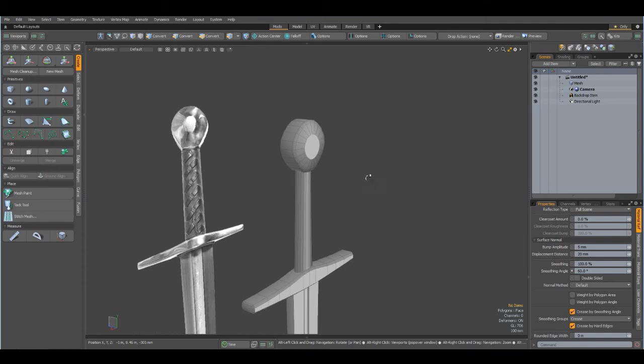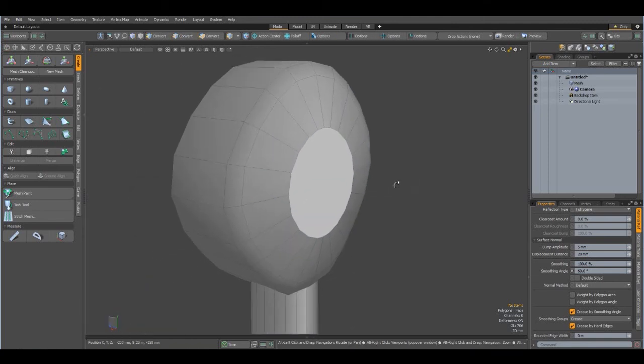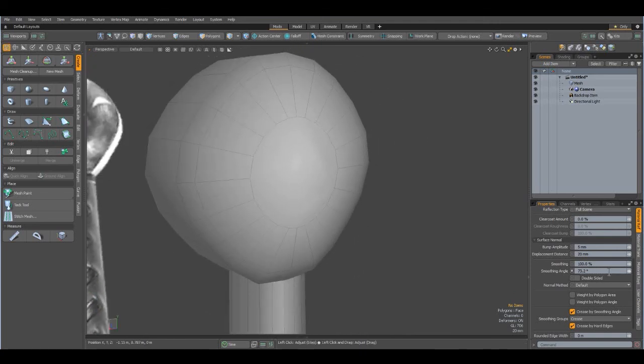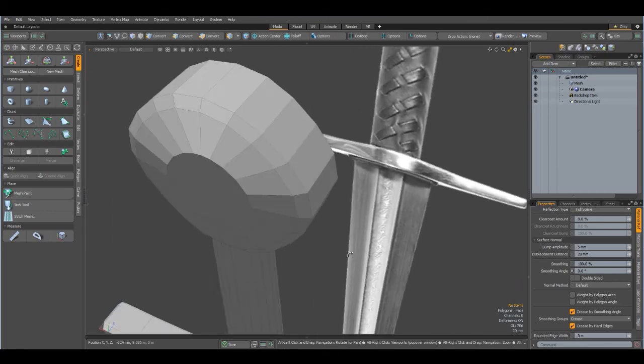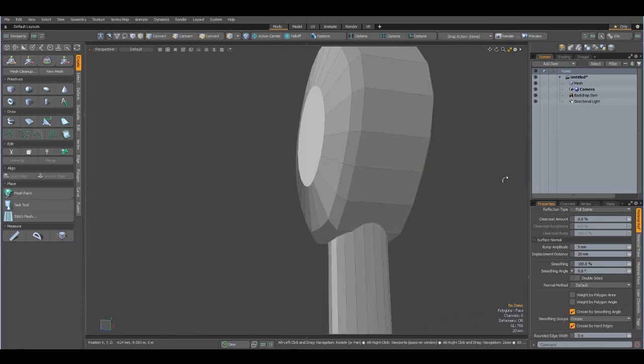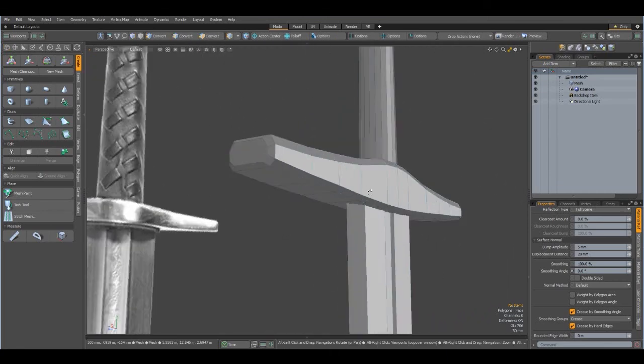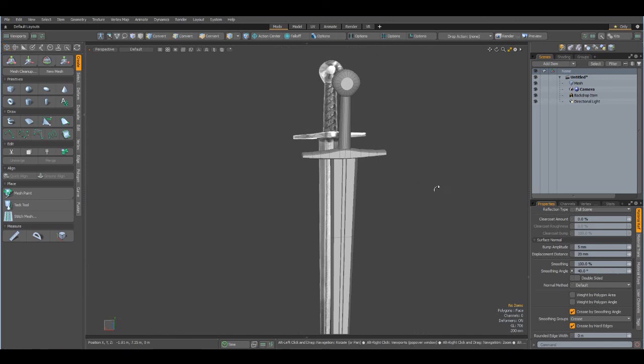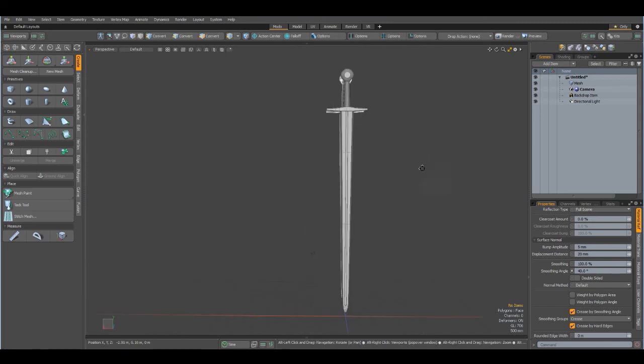The final thing we can look at is shading. If you go to the Material Reference tab under the Properties panel to the left, you can find a property for smoothing angle. This determines at what angle two edges are smoothed together, as you can see. We can just set this to 40 since it works with our mesh, but it can take some messing around with. But alright, let's save it.